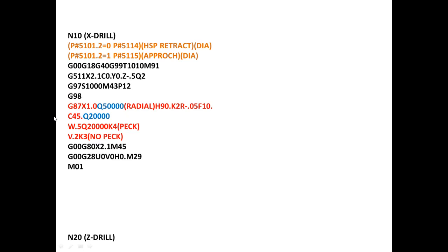And then I will go to the next line. It's still under the G87 pecking cycle. The C-axis will index to the absolute 45-degree position. Now I changed the Q value to 200,000. We didn't change the X value yet. It's still going to go from 2 inch to 1 inch, but this time the Q is 200,000, diameter value 400,000.